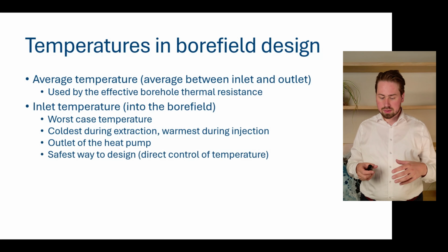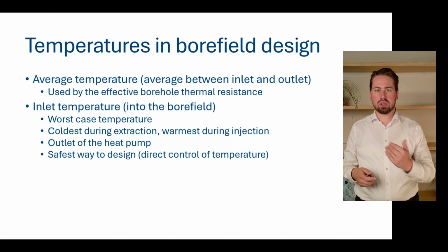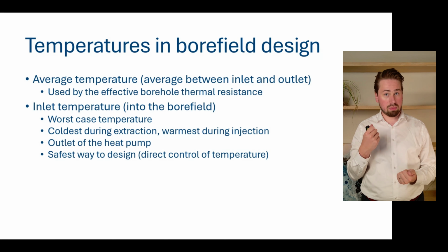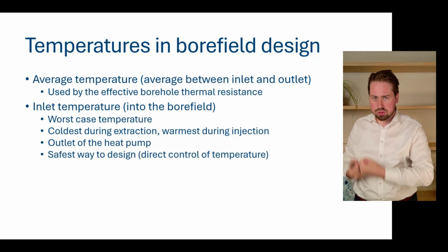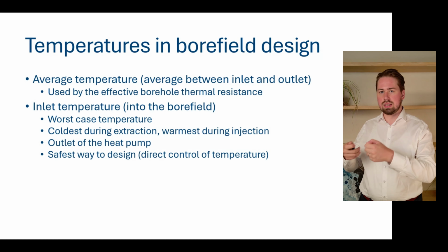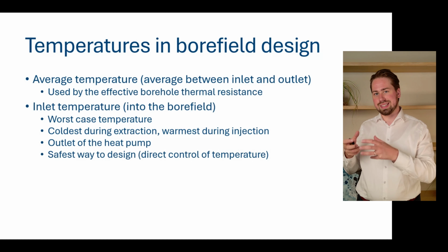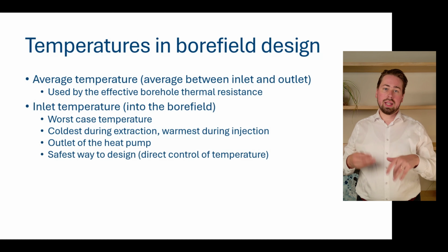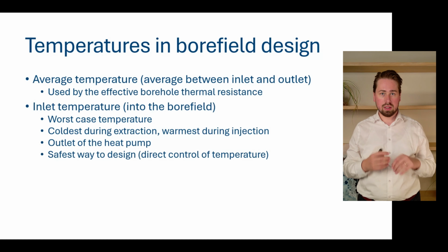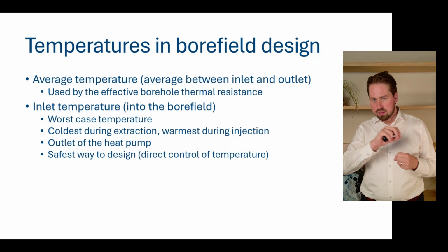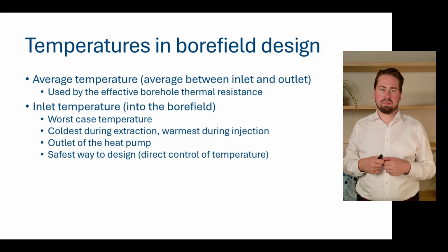And the reason for that is that we have our heat pump, and our heat pump is heating our building. The heat pump gets energy out of the ground, it extracts the energy from the fluid, and this colder fluid with less energy gets re-injected in the ground. And it's this point after the heat pump, right before we enter the borehole, that the temperature is the coldest. When we're injecting heat, and our heat pump is, for example, being used to dump the heat from the building into the fluid, the temperature going into the bore field is actually the warmest of our entire primary circuit.